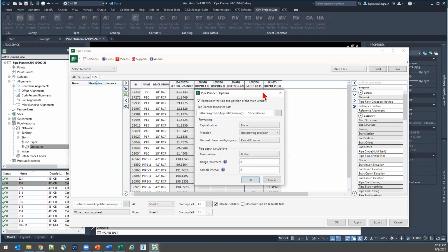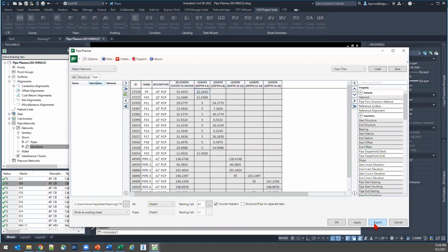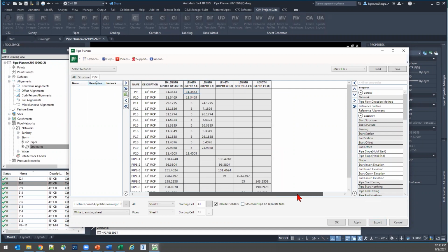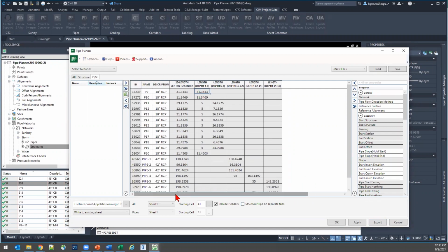So do with this data what you will, kick it out into Excel, run all the formatting that you want to run, and use this tool to help yourself build those manhole schedules, build those compound pipe and structure tables. As long as you have pipe parts and structure parts to read from and all of this data to deal with, you can build whatever table that you want to build.